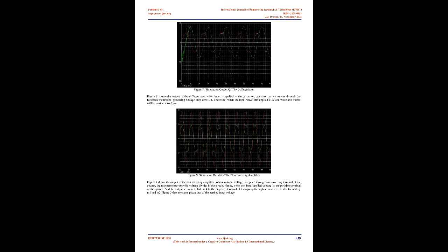This inverting amplifier has many applications such as the transresistance amplifier circuit, and current to voltage converter is a transresistance amplifier. For example, for low power applications, when a very small current is generated by a photodiode or photosensing device, this amplifier produces a usable output voltage which is proportional to the input current.